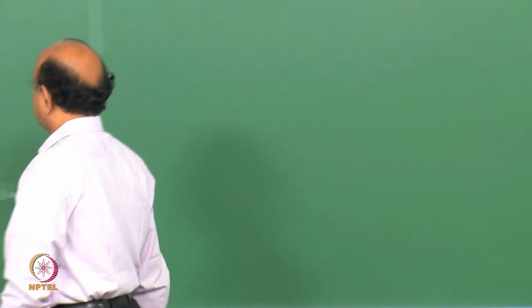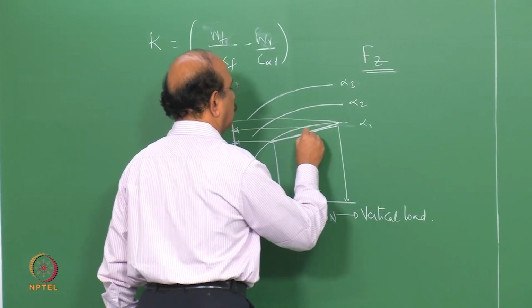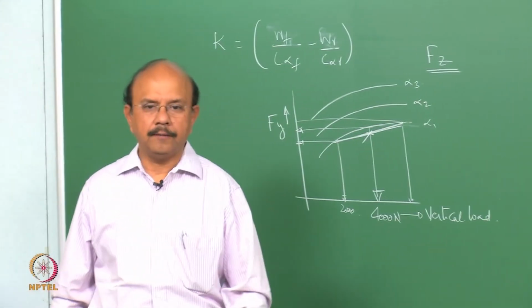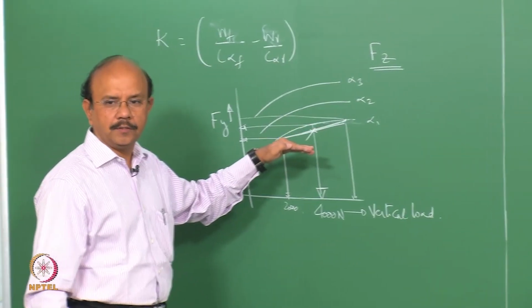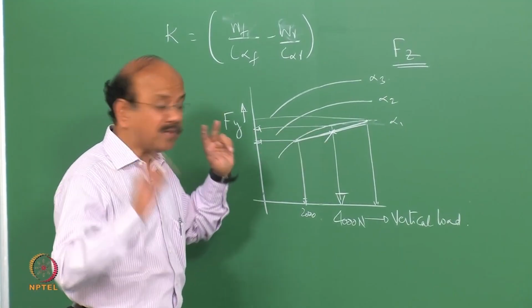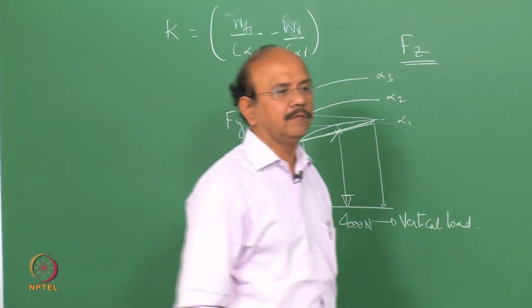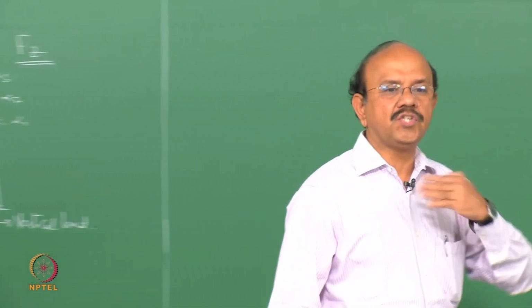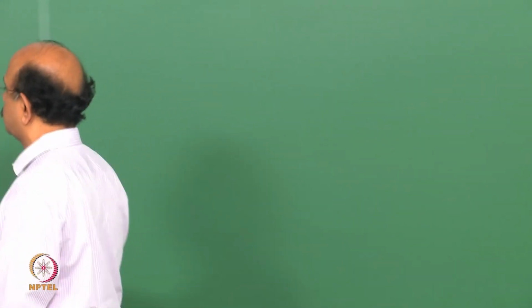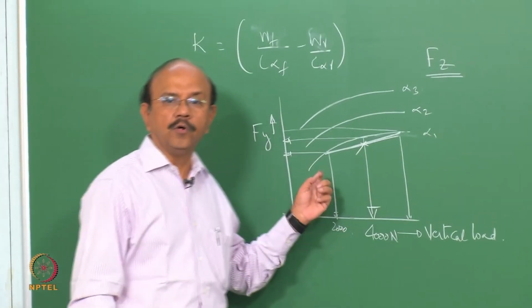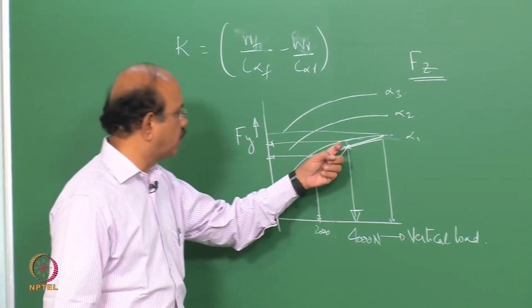Now, this gives rise to a total Fy which is going to be less than what is produced before. In other words, because of the non-linearity of the curve, note this carefully, when there is a change in load, the alpha that is produced is not good enough to equilibrate the centripetal acceleration. It's going to fall short.